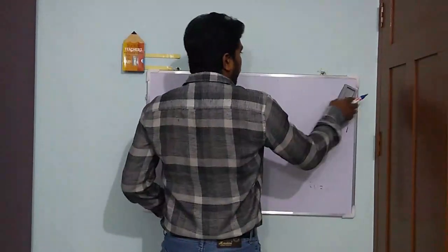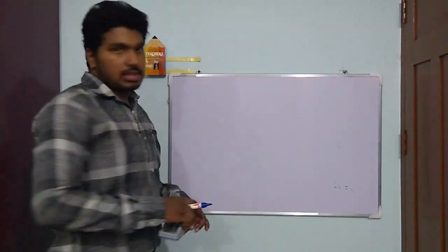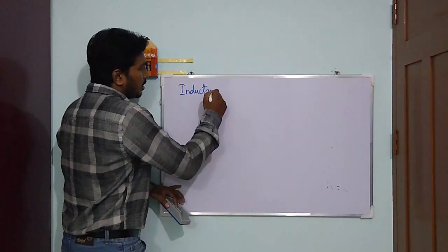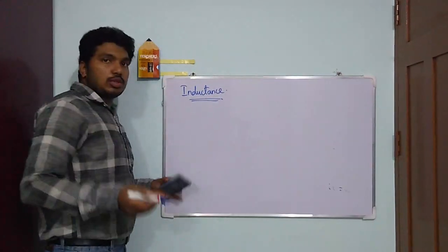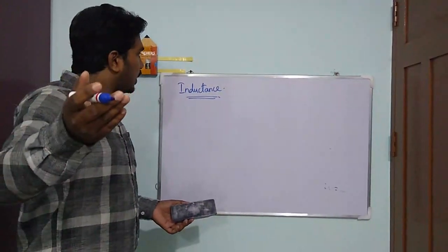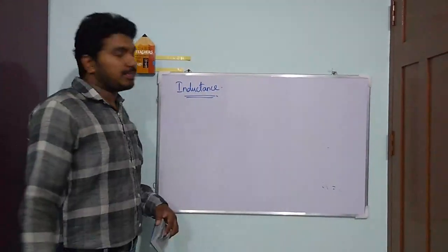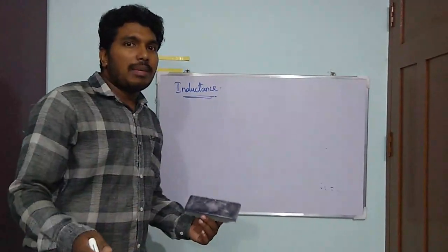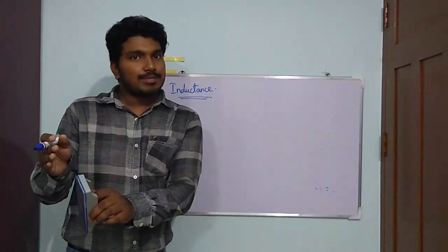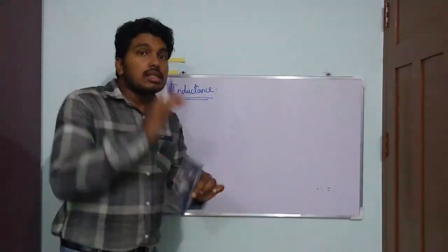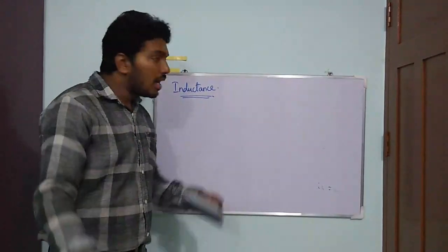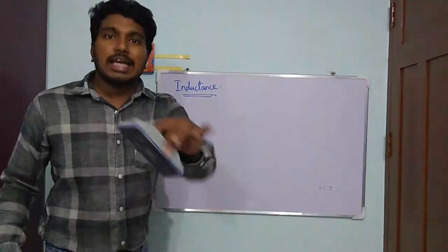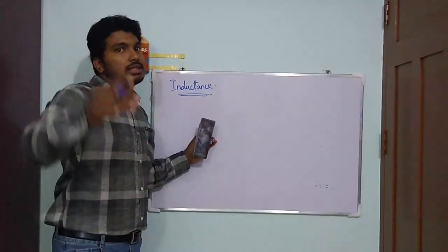That is about inductance. Alright, so now we are moving on to inductance. What actually is this inductance term? When you talk about inductance, it is actually something similar to inertia in mechanics. Inductance is the method of generating an electric current by the change in flux in one coil. By the change in current in one coil, there is an associated magnetic flux change, and because of that, a current is induced in another coil or the same coil. We call this inductance.